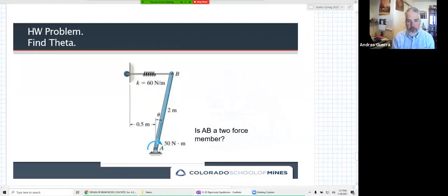And I have a question for you all. Is AB a 2 force member? Well, how many locations do we have with forces? We have A is 1 location and B is another location. So there's only 2 locations, but there's a moment. Okay, so that means it's a multi-force member.